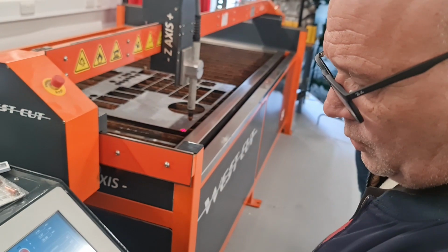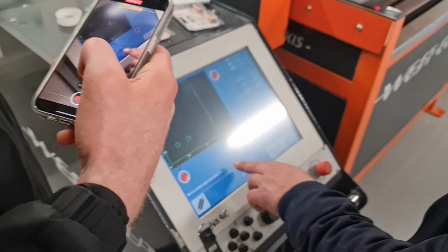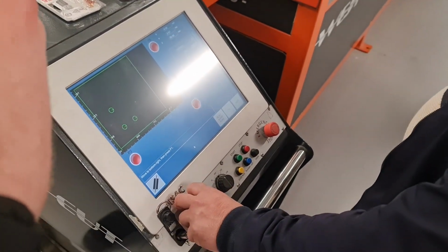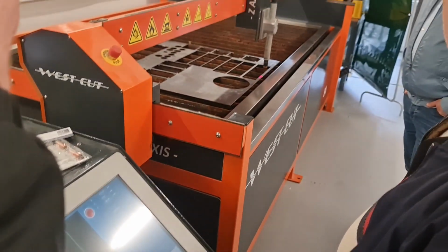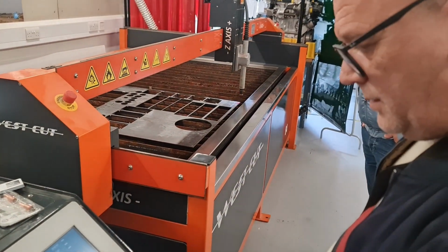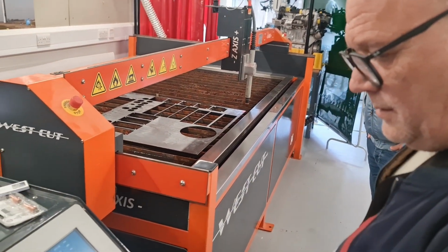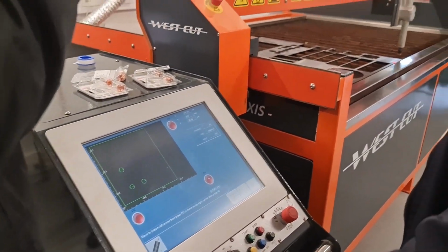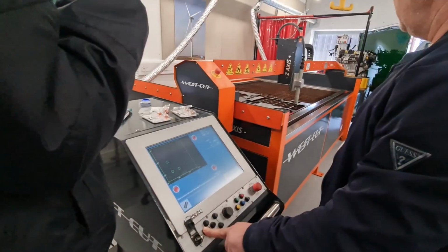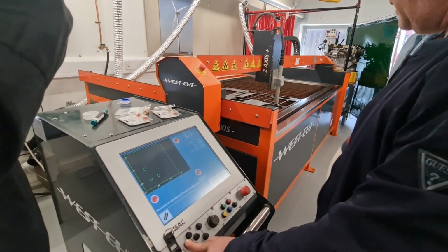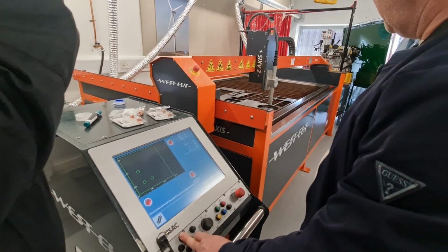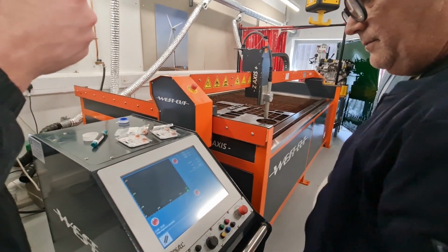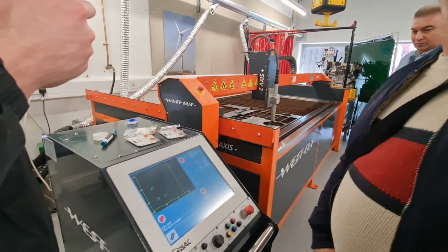And then it will tell you move to bottom right and then press P1. So we are on the bottom right. That one. Okay, P1. Now it will tell you move to P2. So now I'm going to do it on purpose, okay? I'm going to rotate. Let's say the sheet is rotated that way, okay? I will do this one. And it will fit the part on that.